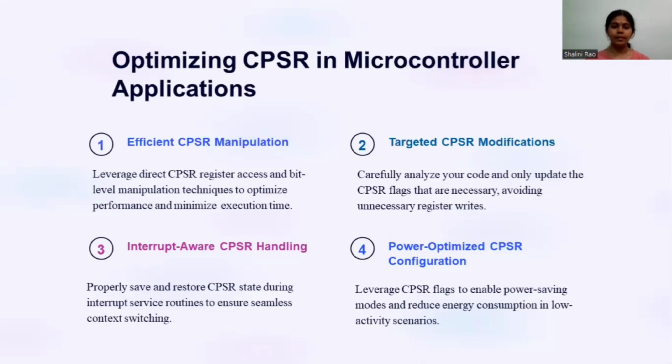Optimizing CPSR in microcontroller applications. Efficient CPSR manipulation: leverage direct CPSR register access and bit level manipulation techniques to optimize performance and minimize execution time. Targeted CPSR modifications: carefully analyze your code and only update the CPSR flags that are necessary, avoiding unnecessary register writes.